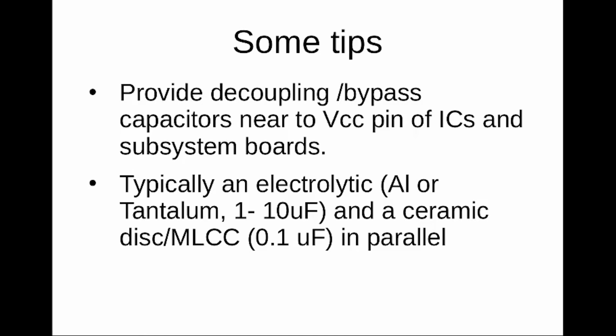Now some tips while developing the hardware. You will have to provide decoupling or bypass capacitors near to the VCC pin of ICs and subsystem boards, and they are typically an electrolytic capacitor or tantalum capacitor in the range of 1 to 10 microfarad, and a ceramic disc or a multi-layer ceramic capacitor, which are basically available in SMD form.